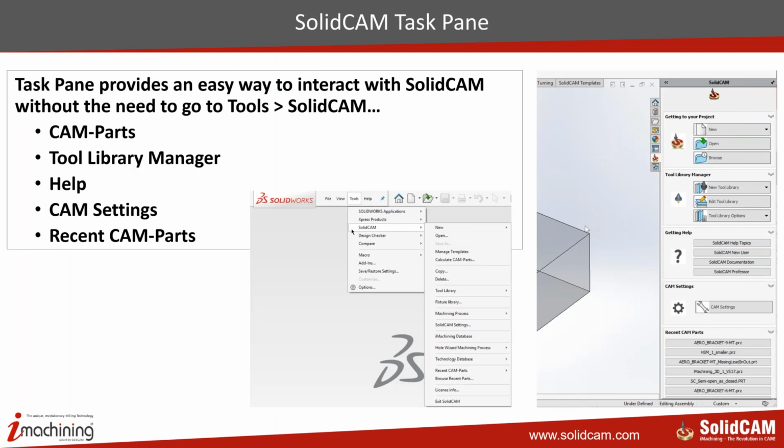The second important general enhancement we have done is the SolidCAM task pane. Instead of every time going to Tools, SolidCAM, New CAM Manager, or Open Recent Part, and doing all these steps one by one, now we have this SolidCAM task pane. On the right-hand side, you'll get the task pane. You can create a new CAM project, open any existing CAM project, create a new tool library, do all SolidCAM settings, and browse recent CAM parts. Everything can be done using this task pane, which is available on the right-hand side of the GUI.